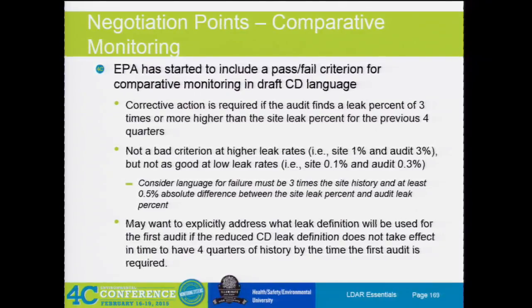Are there other exemptions in there, like if a unit just came online and stuff like that? I know, that would be something you'd want to look into if you're in the negotiation process, I guess. If the audit comes in right after a whole bunch of stuff was added or some kind of upset condition just happened, most auditors will not. Right, a unit that's been upset, until you guys have had enough time to go back in and find the leaks yourself, because it's not a fair assessment when you have that going on. You have a new thermal cycle and everything's heating up and cooling down, and that can really throw off the repair. So every auditor I know would avoid those units.